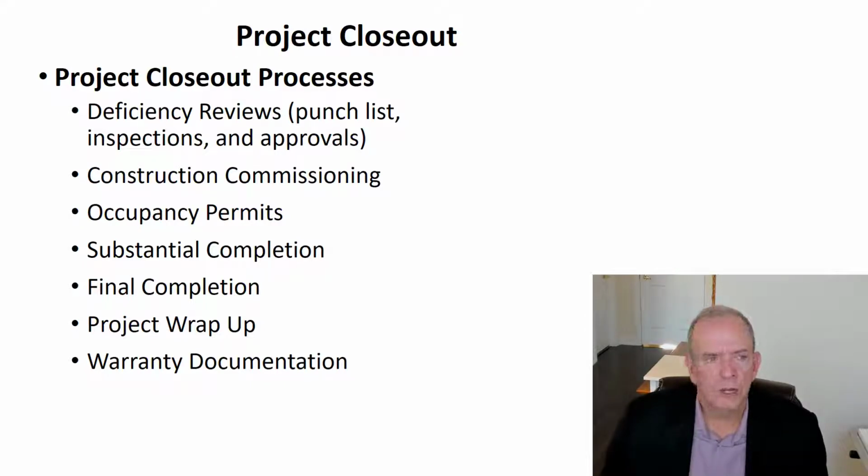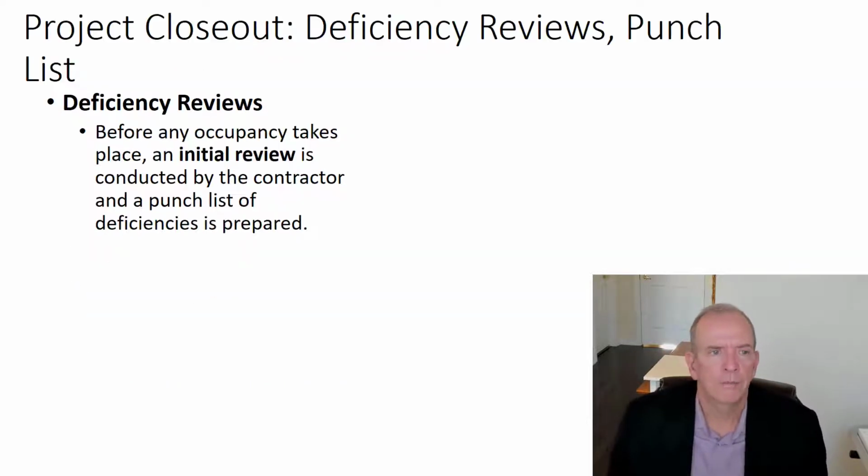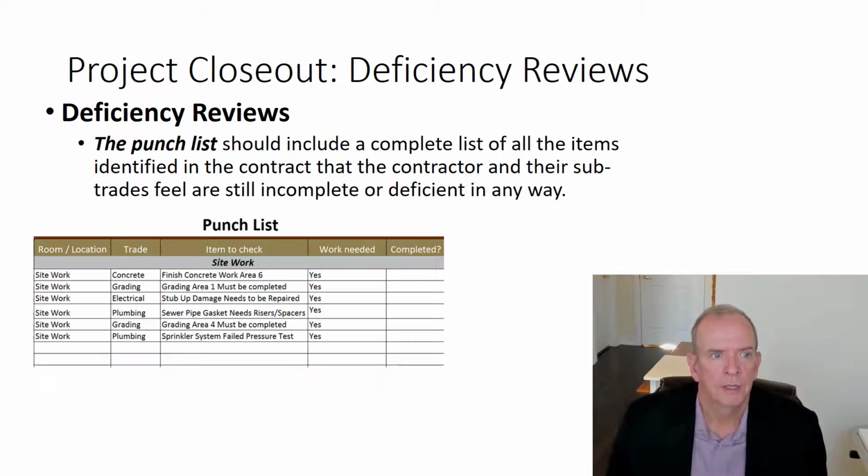And there's a number of points, like the punch list or deficiency list. That's what we look at, all the things that are left to do. So you try to minimize that as you go. Anything that can be done should be done as the project proceeds. Don't leave it till the end. You're always going to have things at the end that you have to do, but you want to minimize the length, depth, breadth and cost of the deficiency or punch list. So you want to do those very carefully.